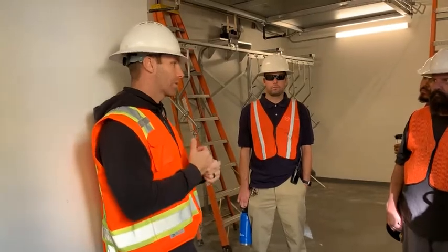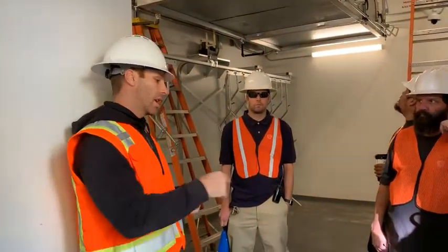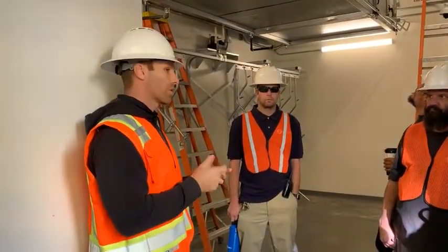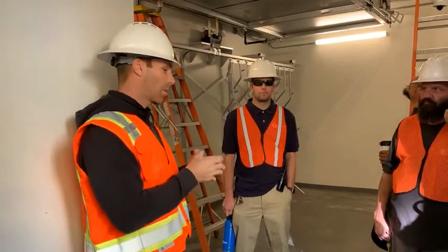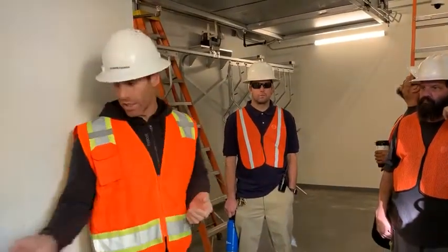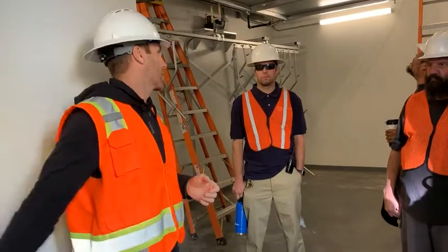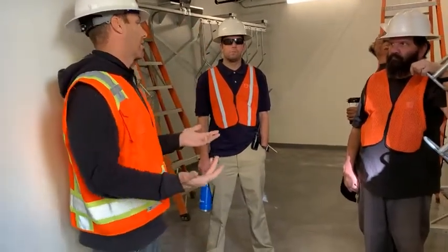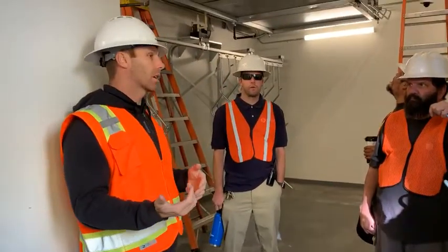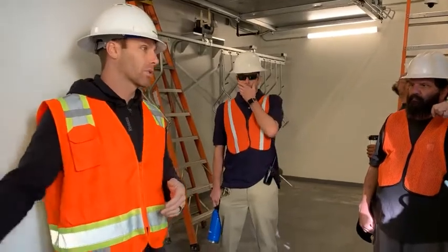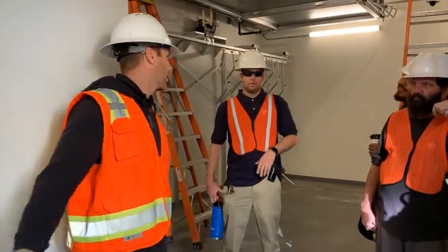The power pack, it's your 120 or 277, and it's a switch layout. It also has a pod on there to create power for the other devices, because all that's in here is a Cat 5. This switch has a Cat 5. That sensor has a Cat 5, that's it. It's got to get power from somewhere. It gets it via the 24 volts DC over the Cat 5.